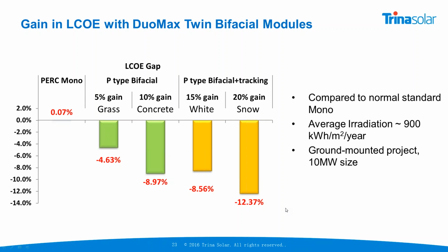So, in conclusion of this presentation, bifacial modules give you a great opportunity to increase the power, increase the energy, lower the LCoE, but the very important thing is that you need to select the right location and design the system such that there is no blockage of the light on the backside. Well, thank you very much for your attention, and I'm happy to answer some questions now.